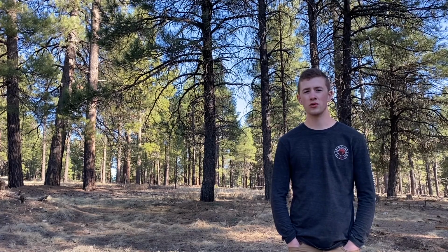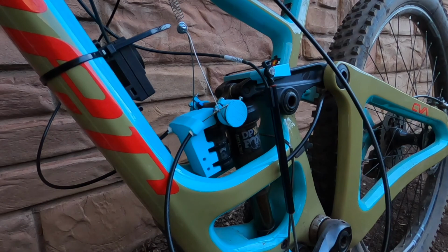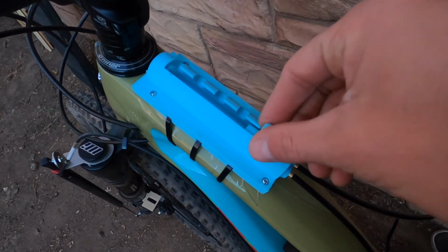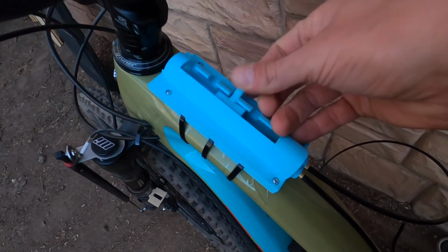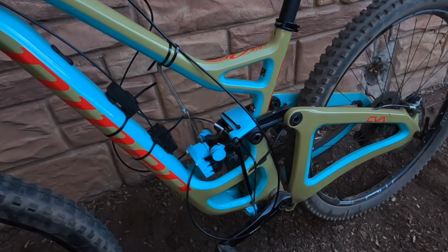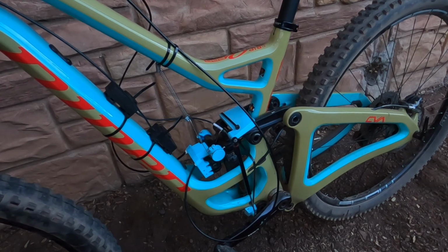After going through the design process, the team decided on a mechanical device that works similar to the shifters on a mountain bike. A user will be able to select what terrain type they're on using a selector switch mounted close to the handlebars on the mountain bike. This will change the suspension settings on the shocks using a cable. The cable is wrapped around the rebound and compression knobs on the rear shock, then attached to a spring to keep it in tension. As the user goes up through the different terrain types, the cable will turn the rebound knob and eventually pull the compression knob to lock out the shock.